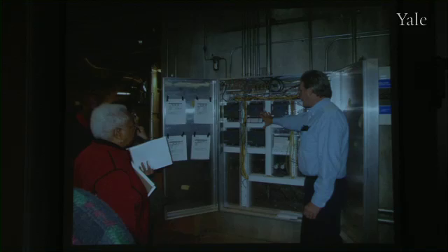The machine I just showed you, the air handler, is controlled via a computerized system, and that's like the little junction box where all the wires that are connected to individual valves and dampers go to sort of a concentration point, and from there they are sent to a computer. So this fellow can operate this library's systems from his office, which was across campus, or anyone in the whole Johnson Controls organization, could be thousands of miles away, can see what's going on and operate it. This is what's called a BMS, or a building management system, sometimes called an energy management system.